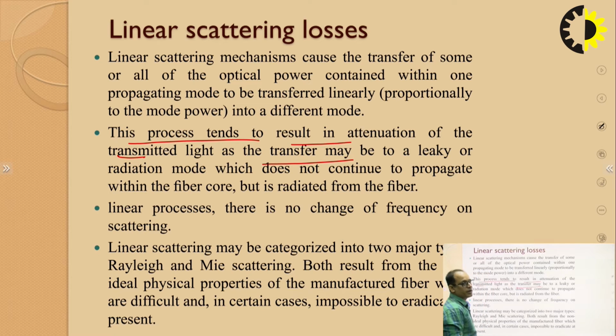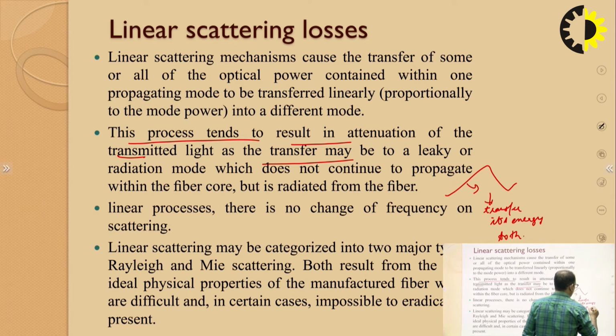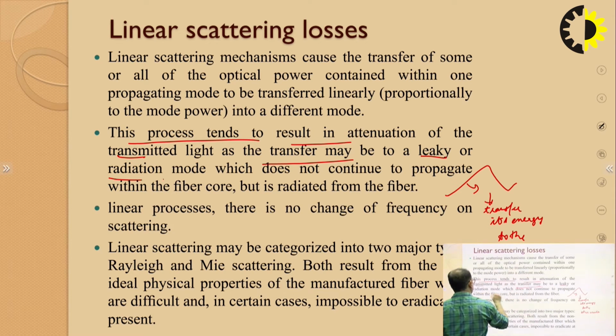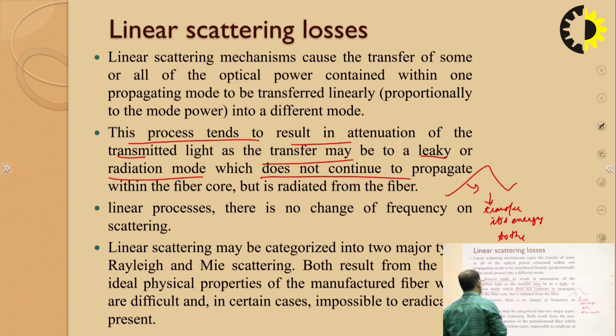So it may happen that one mode propagating inside the optical fiber cable transfers its energy to another mode, and this other mode may be leaky or radiation, which does not continue to propagate inside the optical fiber cable but is radiated out of the optical fiber cable.